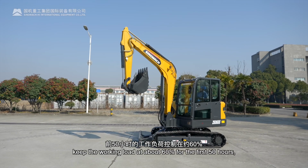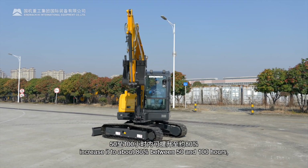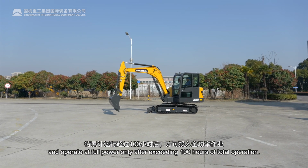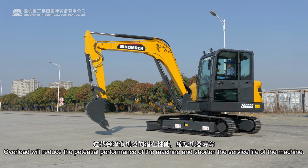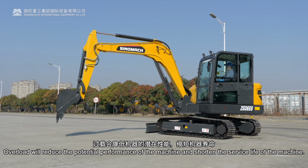Keep the working load at about 60% for the first 50 hours. Increase it to about 80% between 50 and 100 hours, and operate at full power only after exceeding 100 hours of total operation. Overload will reduce the potential performance of the machine and shorten the service life of the machine.